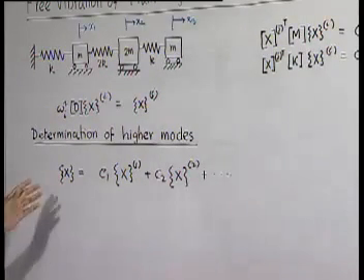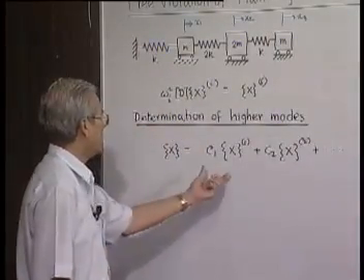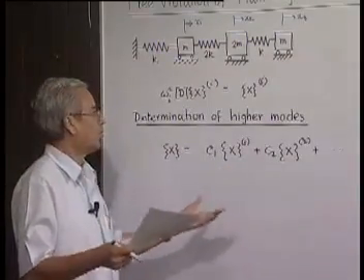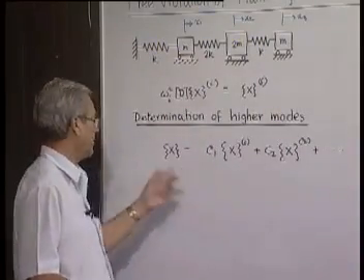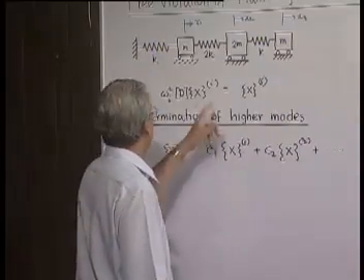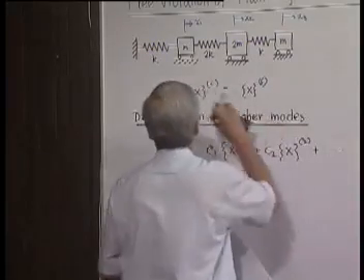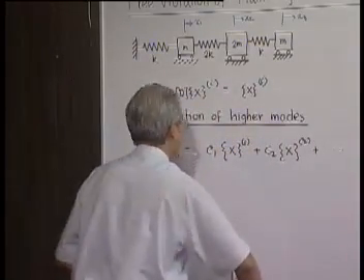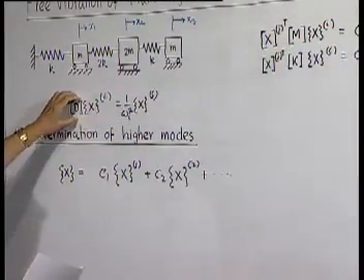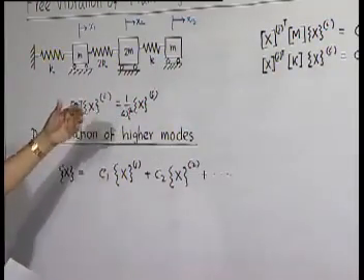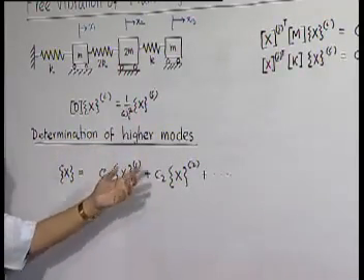Now you see that when we pre-multiply this by the D matrix again and again and again, gradually this term tends to become more and more prominent, because of omega 1 by omega 1 square, by which it is being multiplied again and again for each pre-multiplication of D. So we can express it in this way. Every time we pre-multiply by D, one such term comes, and therefore, as omega 1 is the smallest, this is the largest, and repeated multiplication causes this term to be prominent.